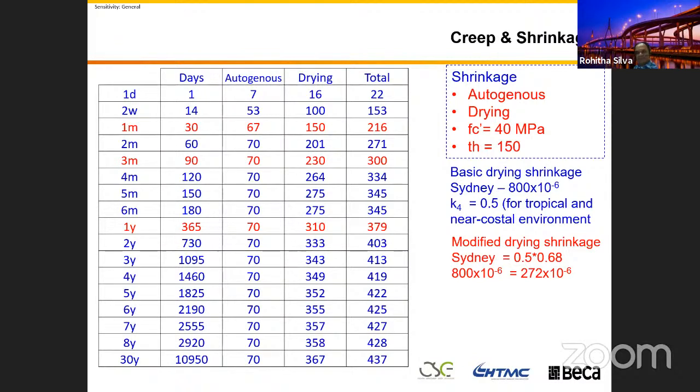If you say 1.5 weeks, you can say at least 4 weeks. So these are actual real construction behaviors. When you calculate, before you erect the segment to the bridge, the creep and shrinkage have all happened. There is nothing left in there. So that's why I said it depends on the type of bridge. You need to pay attention.